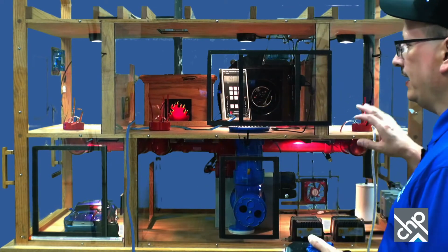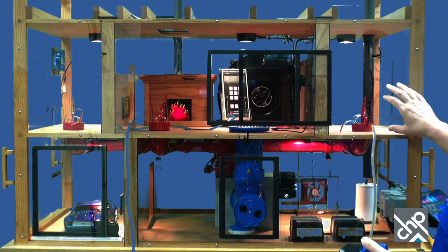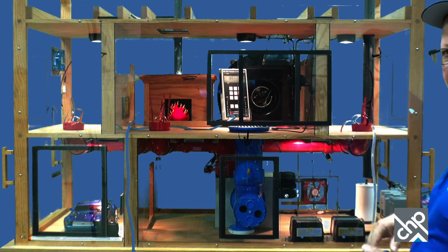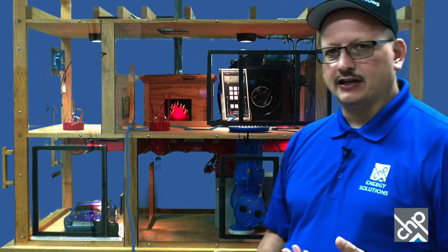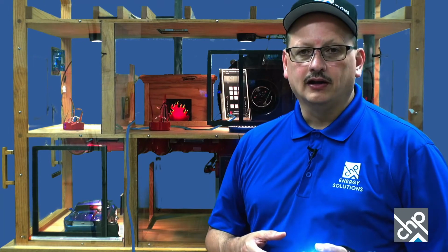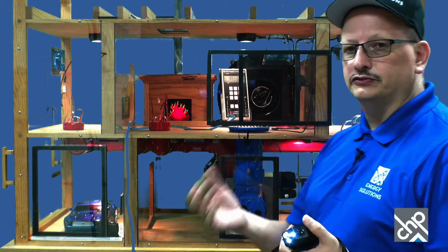Over here in the bedroom, if this room is positive, then it's pushing moisture into the walls. So if you have a cold surface and you got air leaks in the wall, you could actually get some condensation and some things like that. So just by closing that door, and you may be in a house where the door gets sucked shut to a bedroom.